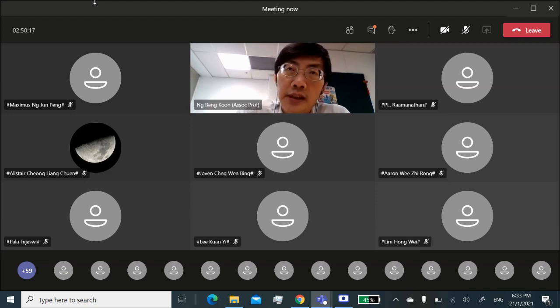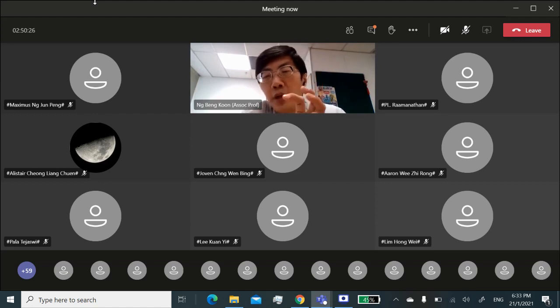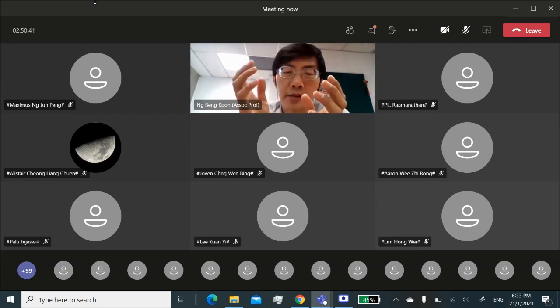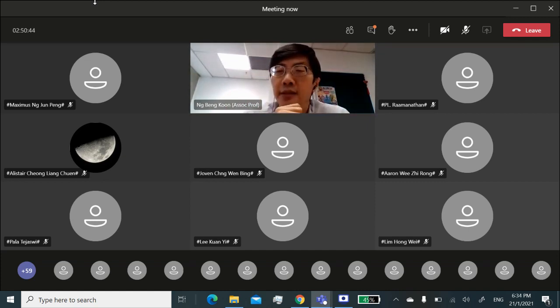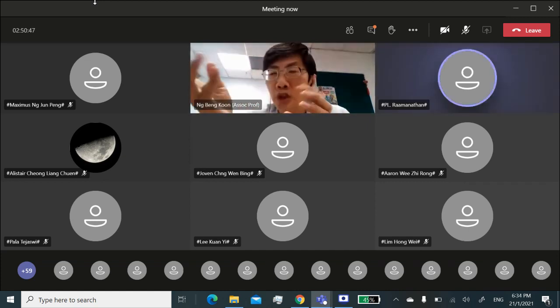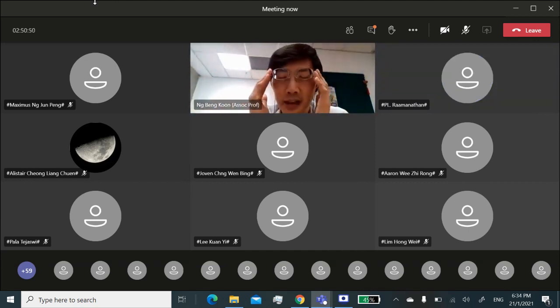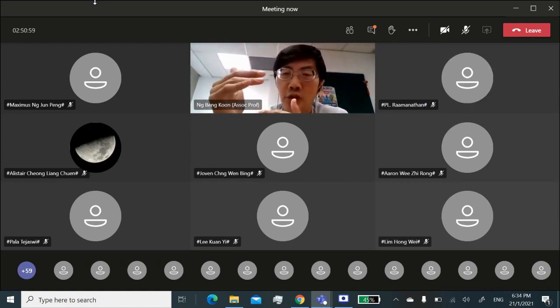The indium and gallium are group 3 elements, and depending on their proportions in the semiconductor, you will have them in alternating positions, essentially uniformly distributed throughout the crystal. But in terms of semiconductor behavior, it's very similar to a two-element compound semiconductor. It's just that in some positions instead of gallium you have indium, which is still group 3. These slightly different elements actually affect the band structure of the semiconductor, and you can use that to adjust the band structure to suit your need.